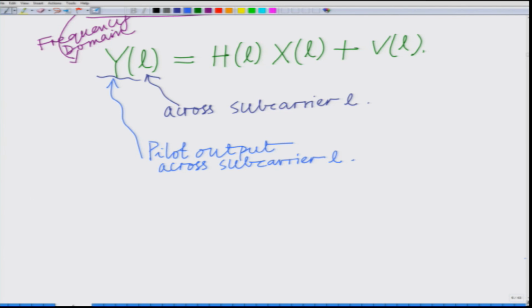So, what we have done so far is we have considered a simple N equal to 4 subcarrier OFDM system. We have loaded the symbols capital X0, capital X1, capital X2, capital X3 onto the subcarriers, that is, performed the IFFT or the IDFT to generate the time domain samples, added the cyclic prefix, and we looked at what happens at the receiver once you take the FFT.